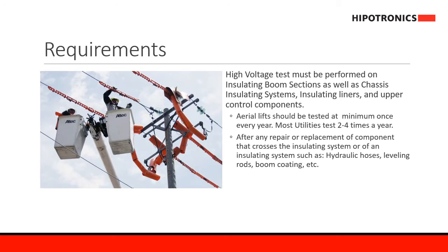High voltage testing is performed on insulating booms, chassis insulating systems, insulating liners, and upper control components. Aerial lifts should be tested at minimum once per year and after any repair or replacement of components that cross insulating systems, such as hydraulic hoses, boom coatings, and the like.